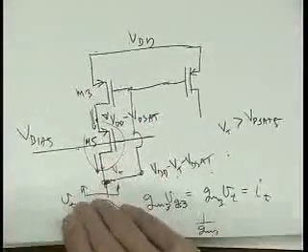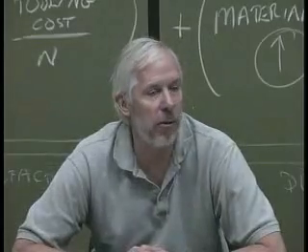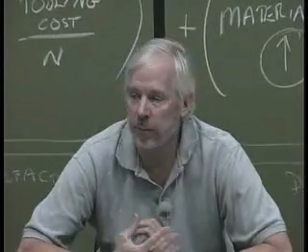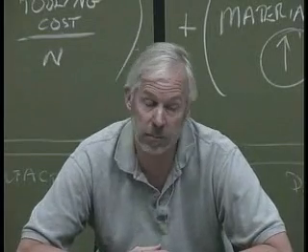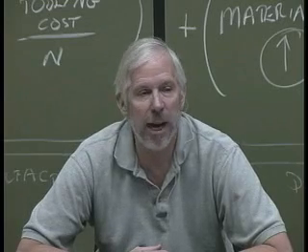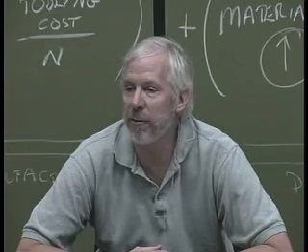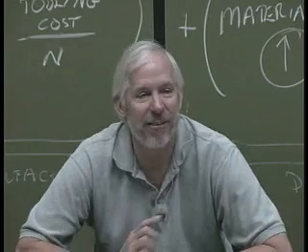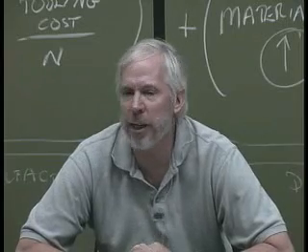Frequency response, not having that as part of your circuit design, is leaving out a really big step. Now we get to build circuits with all the constraints. Your next design problem will have frequency response in it. And now you won't be able to go to 1 picoamp of current and get gains of 1,000,000, because you'll find the circuits will run too slow. So now you're becoming real designers. Any questions about this other stuff?